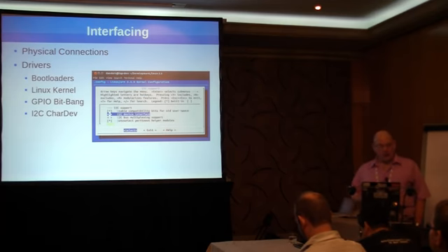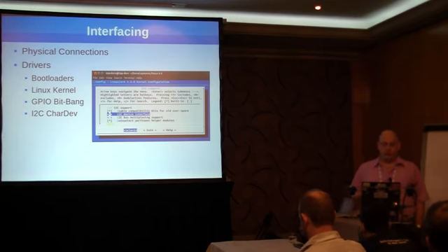So in addition to the core drivers in the Linux kernel, we actually have an I2C character device that will allow you to access I2C devices on a bus from user space. Now, I don't recommend doing that generally if you're going to write a user space driver for a device or work directly from user space for I2C, but there are specific instances when it can help you. When you're prototyping your driver or working with a new piece of hardware, the I2C character device can make it very easy to debug and work with it. In addition, there is a group of tools from user space that can help you do that.